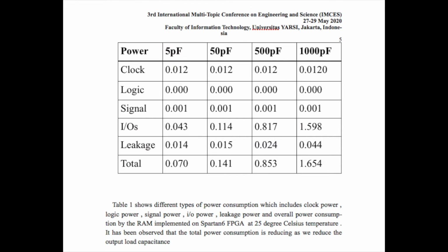We recorded our observations first using LVCMOS 25, that is VCCO, or input output voltage, set at 2.5 volts. We kept increasing our output load capacitance until the device becomes unstable, and we found out that the thermal stability is intact up to a maximum of 1000 picofarad. The observation table shows that the logic power consumption is nil at a minimum of 5 picofarad and even at a maximum of 1000 picofarad. Testing at 50 and 500 picofarad, the logic power consumption is still zero and no change is observable in signal power loss, where the value is 0.001.